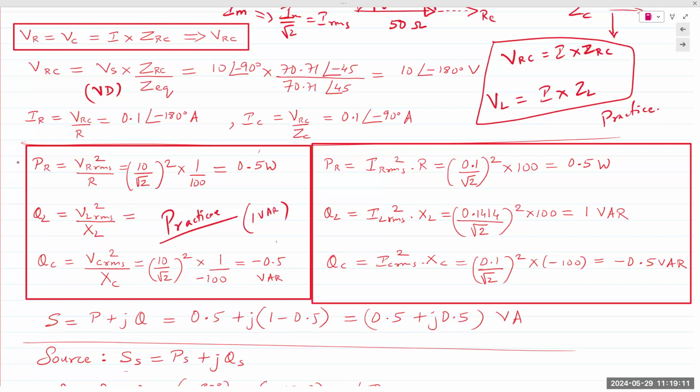So the question being asked is, does the phase angle matter or not for the power? The answer is, it does matter. These are complex numbers, complex quantities, so phase angle always matters. It depends on the equation. If you're taking just the equation for VC over X, then it's just the RMS value divided by the reactance. So that's just the RMS values. Then it's just the magnitude, so there would not be any angle.